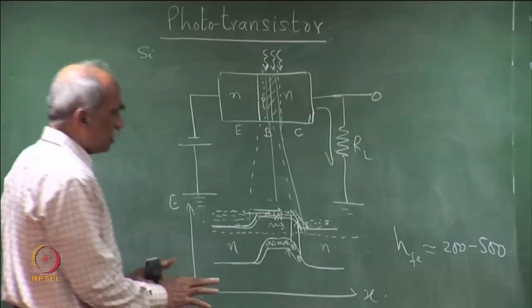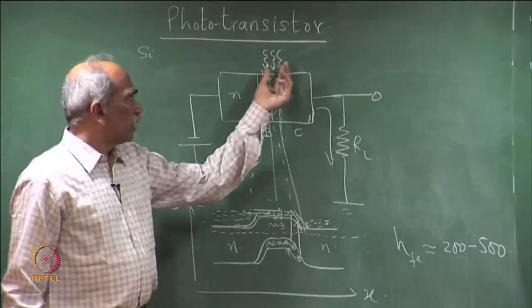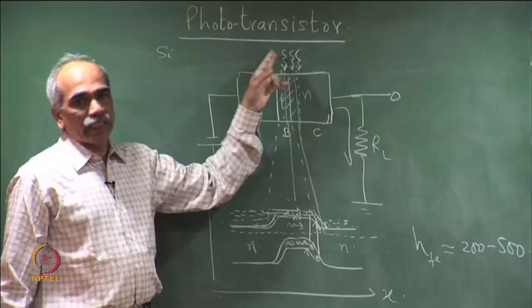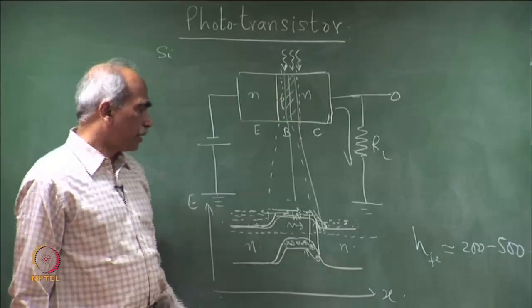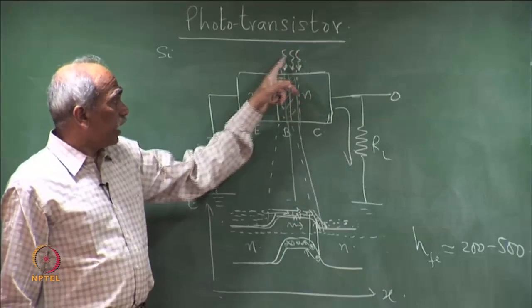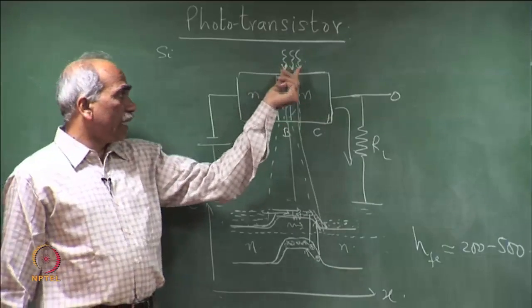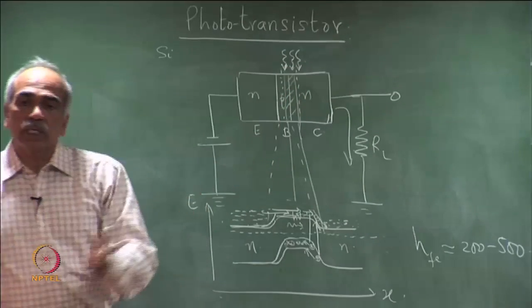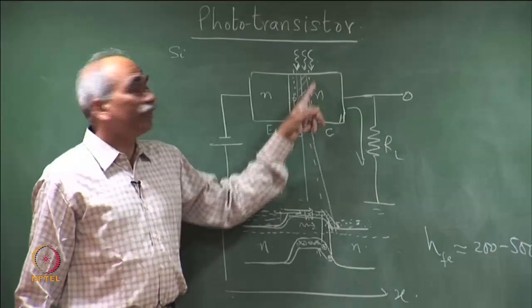Phototransistors are used in simple applications where a sufficient amount of light is incident, because one of the primary demerits of the phototransistor is that the catchment area is very small, since it is at the base-collector junction, which is the active region.